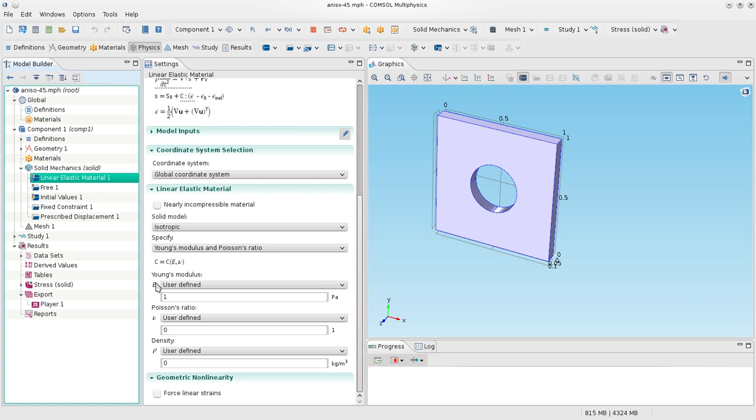Now notice that first, the Young's modulus is chosen to be 1. Don't worry about the units. This is Pascals, it says, but it could have been gigapascals, or this could have been 100 gigapascals, which could be more realistic if this were, say, metallic. Ultimately the value of the Young's modulus is going to only scale the stresses I measure for a given deformation. So for numerical purposes, I'm scaling down the stresses, and the units of stress here are assumed to be of the order of the Young's modulus. Whatever the units are.